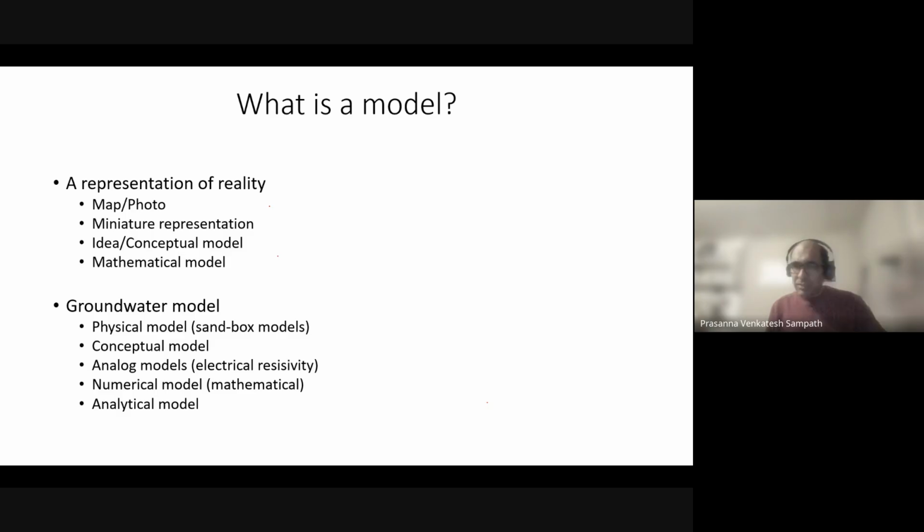Now, I'll not spend too much time on this, but basically, if you think about it, our fundamental equation, Darcy's law, looks like this: Q equal to minus Ki, right? Now, in electricity, we have a similar equation, right? V equal to IR, very similar to Ohm's law. Okay, these two equations, if you look at them, they look about the same.